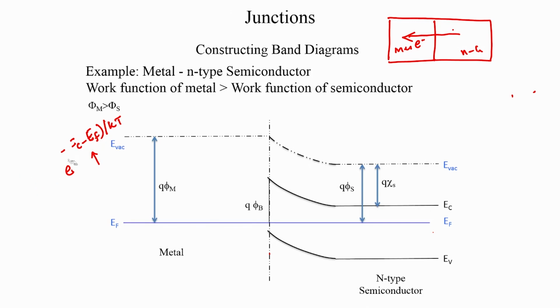So, essentially what we do is you first align the Fermi levels and you just mark out which of the materials is going to donate electrons. Where is the electron going to flow from? Is it from the right to the left or left to the right? And depending upon which material has lost electrons and which material has gained electrons, we adjust the band position, the EC minus EF location in these two materials, and therefore you get a bending of the bands in space.